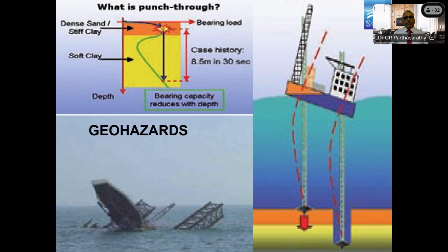If all the legs penetrate simultaneously, perhaps it's not intended but could be okay, but we are not sure of the thickness of the crust at each of the leg locations, which could be around 40-50 meters apart. If one of the leg locations has a thinner crust which breaks first, then that leg will punch through or penetrate first, where the ship will tilt to that side, which creates a leaning instability and changes the center of gravity, and you will have accidents happening.